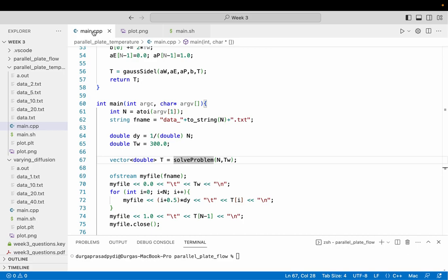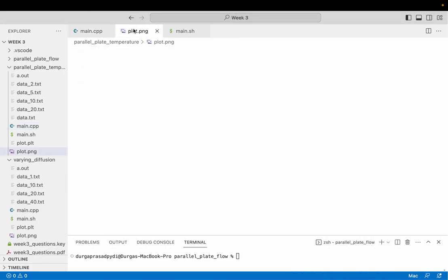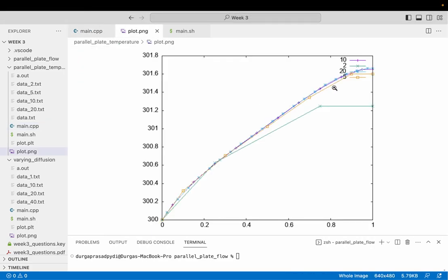So now it's adiabatic, right? Yes, adiabatic. Say the fluid is initially at zero temperature. Slowly the heat has to flow and the temperature has to increase, right? Yes, temperature will keep on increasing towards your adiabatic end, and near the wall it will be flat because it is adiabatic. It shouldn't have any slope as a function of y, right? So it will keep on increasing, and near the adiabatic wall it will flatten out because ∂T/∂y equals 0. That is what you will get if you do not have any flow.